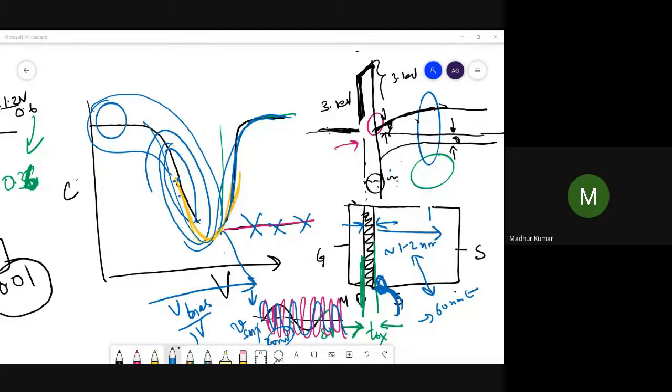So for a MOS capacitor, when we ground body and gate, we give the reason for band bending as satisfying that 3.1 volt electron barrier and matching the Fermi level. But when the gate voltage is not zero, do we say that band bending also happens because we need to satisfy the shifting of bands due to the applied electric field?